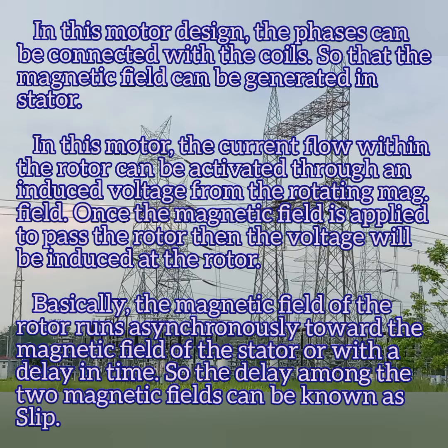In this motor design, the phases are connected to the coils so that the magnetic field can be generated in the stator. The current flow within the rotor is achieved through an induced voltage from the rotating magnetic field.